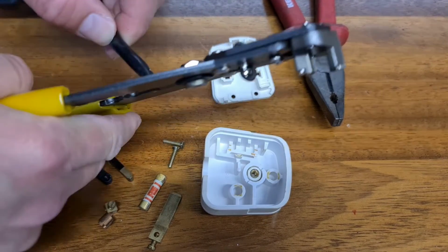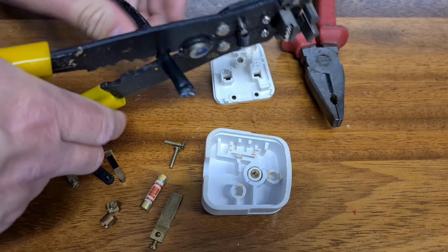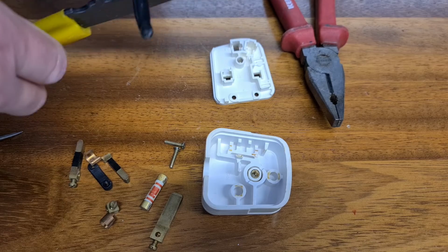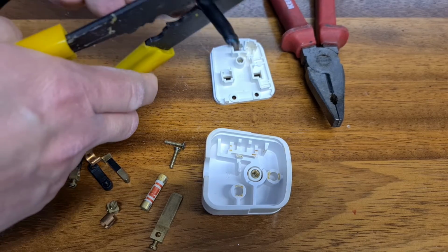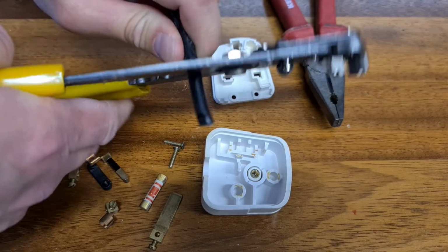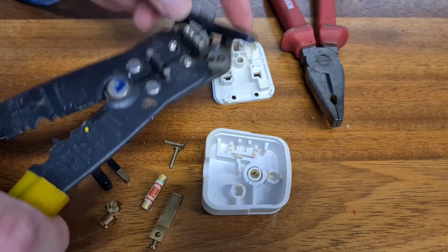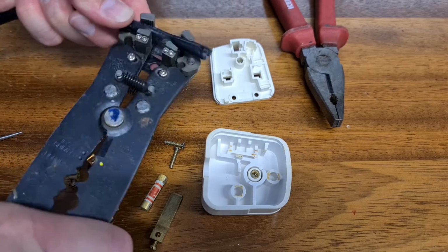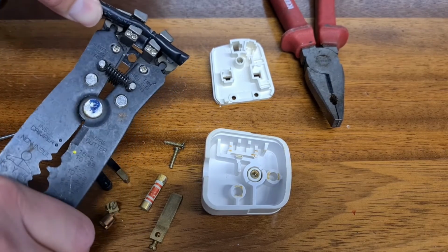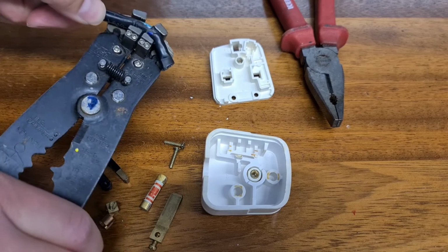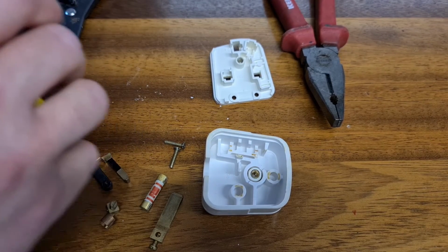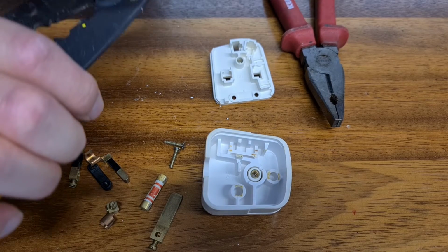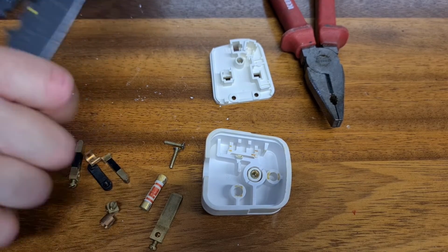So the very first thing I'm going to do is, it makes it easier to strip the wire if I slightly stress the cable at the point where I'm going to strip it. And I'm going to do that by half squeezing the wire strippers at that spot. Then I'm going to place it in the jaws, and hopefully it should break it at that point. And I might have to put it in a couple of times. You can see I'm getting good. I might have to pull it a little bit, but I'm basically getting a good separation of the outer layer of insulation.